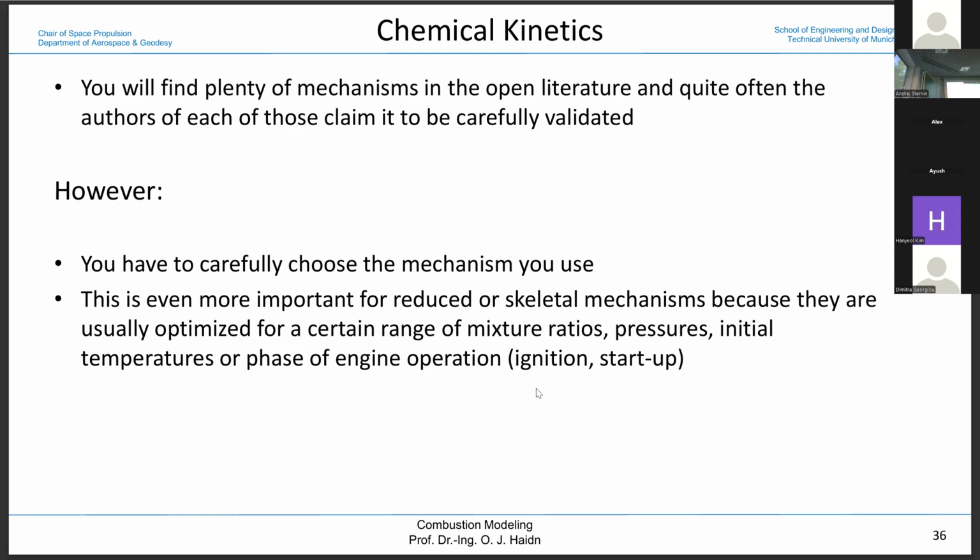So at the end, typically the normal flamelet would mean that I predict the chemical equilibrium and store it in a library. And this would mean we have a mixture fraction, the variance of the mixture fraction, and so on, so 4-dimensional. In non-equilibrium, they would have a 6-dimensional library to be more predictive. So you can do that.